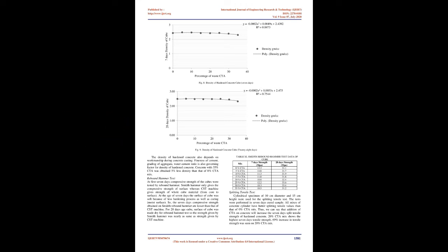Fineness test. The fineness test of cement was determined following steps outlined in IS 4031 Part 1. The fineness value obtained is 3.85. Setting time. The cement sample was found to have 55 minutes for initial setting time and 325 minutes for final setting time. This is in between 30 minutes and 600 minutes.